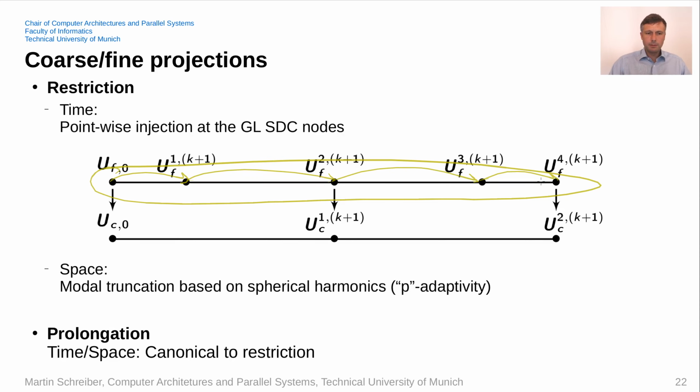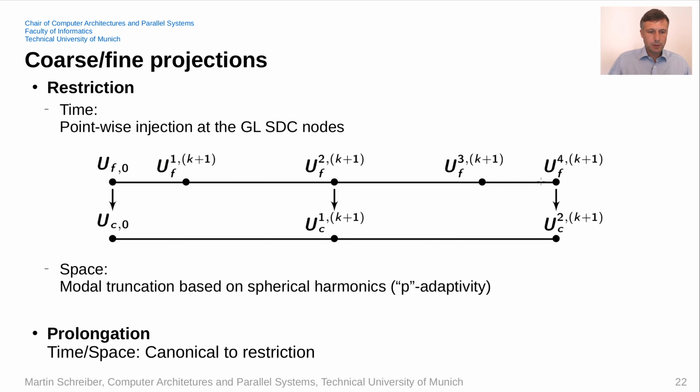And we would do that as a first test run. That's just a first order accurate method which we would apply here, which should run really fast. And then, because it's just first order accurate, the solution is taken here at these quadrature points. That works nicely if you use these Gauss-Lobatto quadrature points. Then we use a restriction down to the coarser resolution.